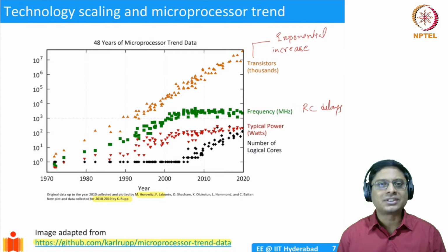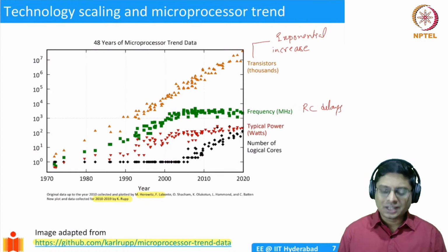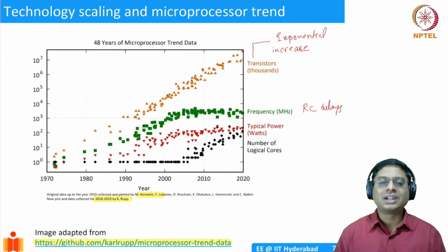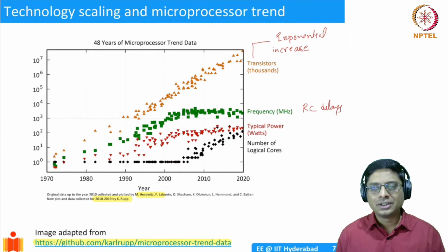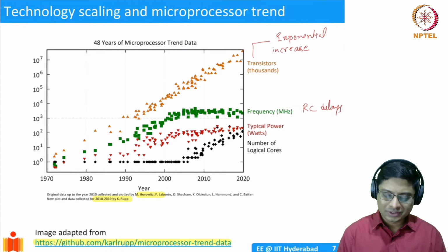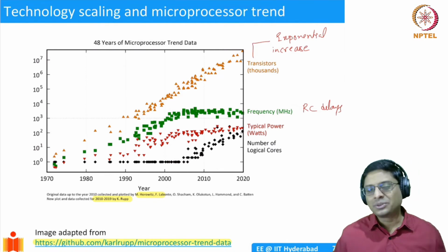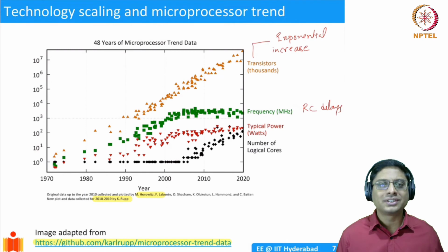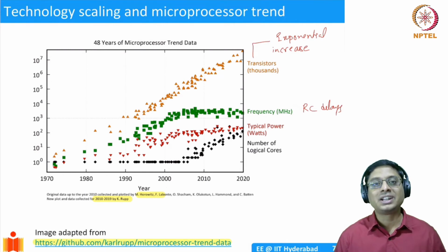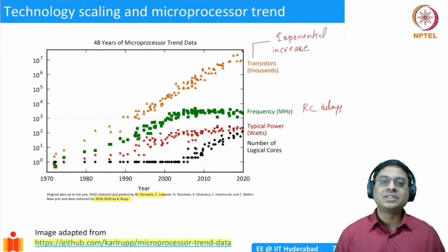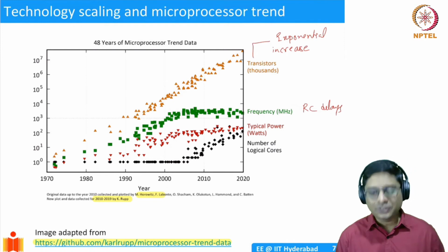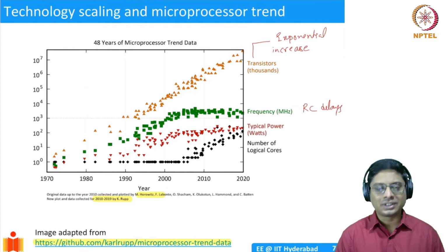Ideally, we want to do it instantaneously, but the current limitations of the technology don't permit it. So we are not able to go beyond this frequency. We can do it at a single transistor level, sure. But once you integrate, let's say, 1000 transistors, it's very difficult to achieve very fast switching speeds, especially with silicon. There are other alternatives, but with silicon it is not that easy to increase the frequency more than these few gigahertz.